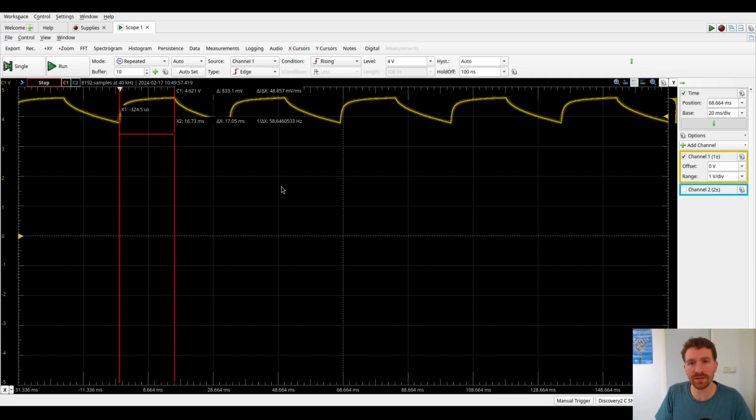So this is kind of interesting and cool for a number of reasons. One very obvious one, and this is kind of incidental but also kind of nice, is that these two circuits are completely isolated from each other, right? So the power supply and the oscilloscope and everything is completely disconnected from the circuit we're trying to observe. So that's just an interesting thing. This is a passive way of reading the signal. We don't have to invasively get in there and actually physically probe the board.